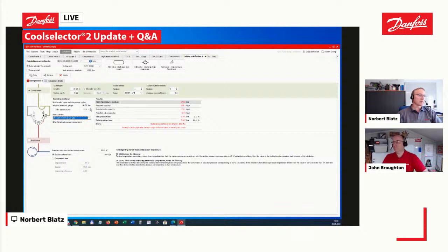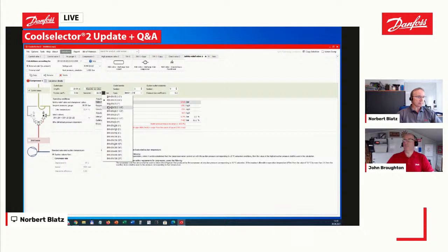Then one thing that will happen is a new type, an SFA 10H for CO2 high pressure application, appears, but also a detailed calculation and a warning, if necessary, about the velocity and pressure levels in that outlet pipe. Having this information enables you to change the diameter to a larger one to get rid of these issues.